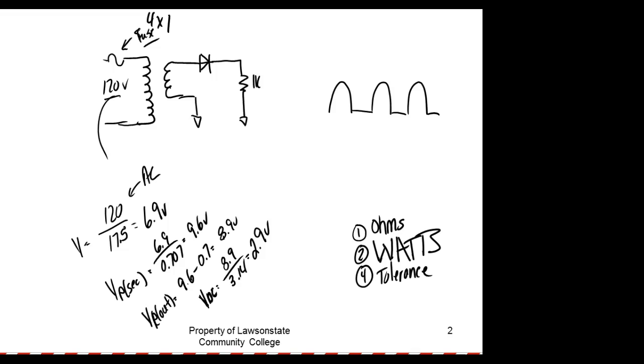So normally when we troubleshoot, we start on the output. I came over here and put my meter right here. It measures 0 volts. Where would I go to next? Measuring voltage, all we're doing is checking voltage. I'd go to the source, so I'd go here. What we do is move from the output back toward the input, right?